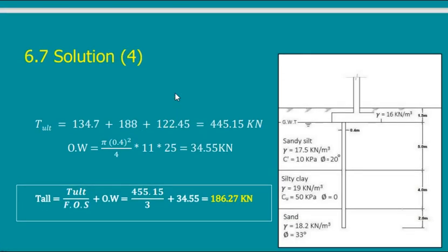We need to say that to calculate the tension load of the pile, I use the friction regardless of the method that I'm using. If I'm using a method that does not differentiate between tension and compression, then use the value divided by the factor of safety if you have the ultimate to get the allowable, then add the own weight of the pile.